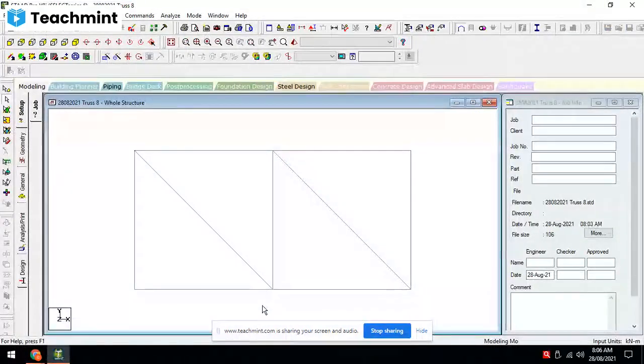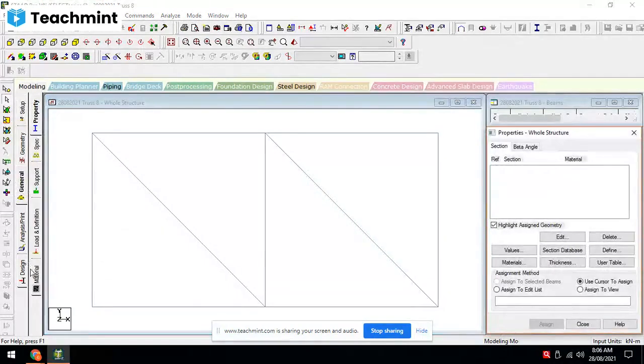So this is the truss. Directly go to the structure wizard. Click on the required model. Then put the length and the height, and width is 0 because along the z-axis we are not taking any dimensions or any member along the z-axis, that is perpendicular to your screen. So it is a two-dimensional structure, right? Then General, click on Material.